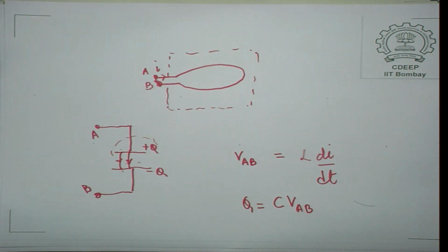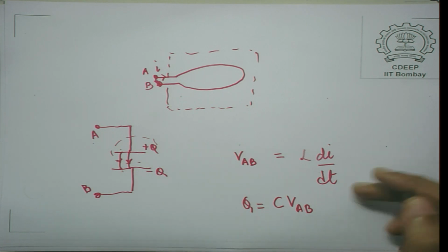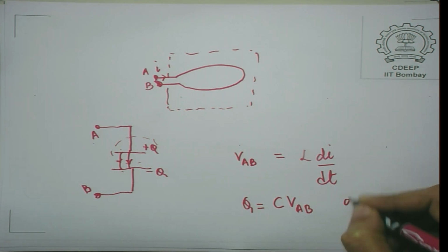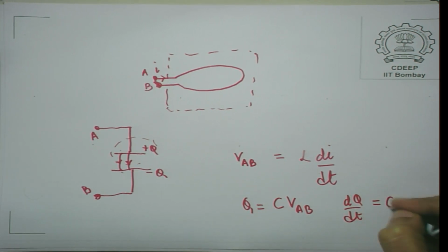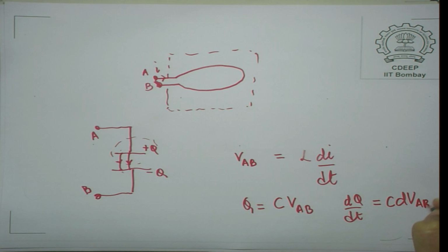So, actually you can compute the electrical field; there will be an electrical field between the plates. Because of this Q is equal to C into V_AB, the current, which is nothing but the rate at which charge flows through a cross section, is equal to C dV_AB by dt, assuming that the plates are not moving themselves.